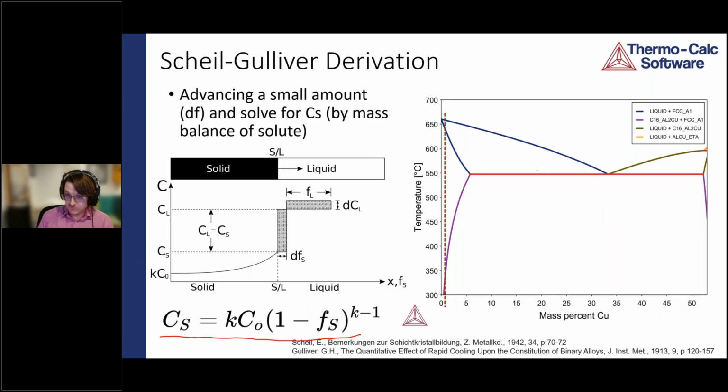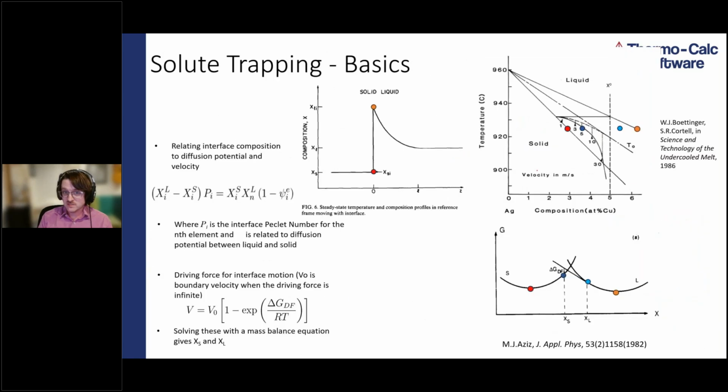And when you move very, very quickly, solidification-wise, the interface is not in equilibrium. And so that is the part of the Scheil that needs to be modified, okay? And again, I'm not an equations guy. I won't try to go through the derivation, but graphically, if we plot as a function of distance, here it's distance is z, sometimes distance is x. I guess it's not x because we have x for chemistry here, but anyway, a solid liquid interface will